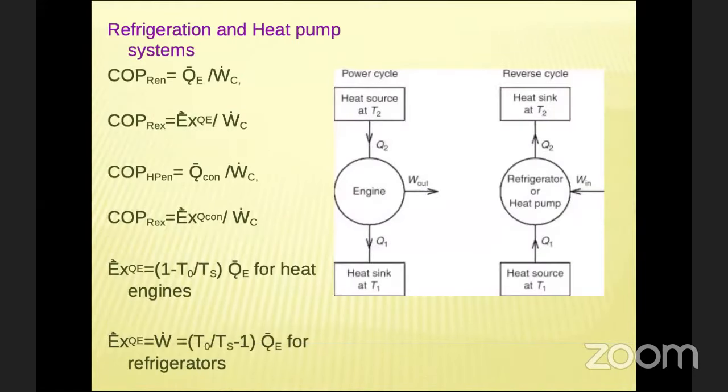And this is another thermodynamic system, called refrigeration. Kelvin contributed for the heat engines, and Clausius contributed for the refrigerators and heat pumps. All right, the Clausius statement and Kelvin statement, we know that. For performance, we are using the term coefficient of performance, COP with suffix en or ex, that is energy based and exergy based. For the COP of a refrigerator, energy based, it is Q by how much heat it is removing with the given work input. And exergetic means we have to talk about the thermal exergy, how much is removed with the given input.